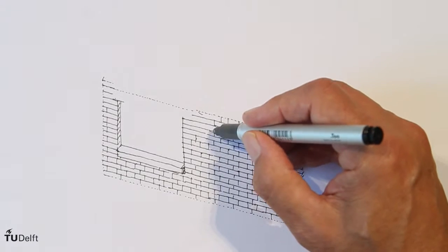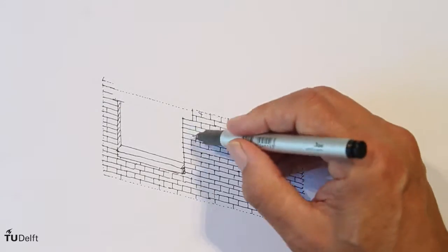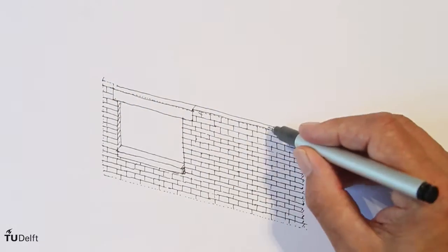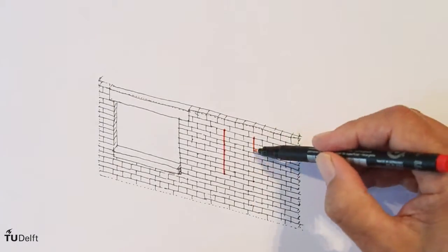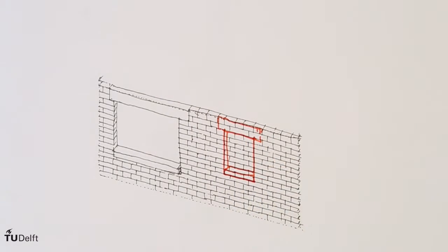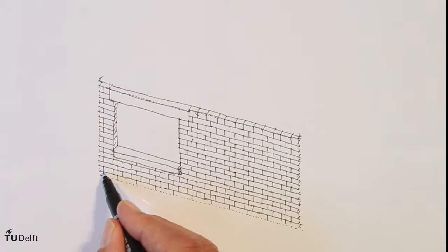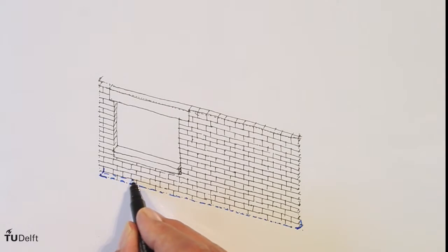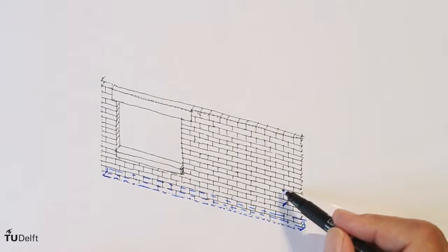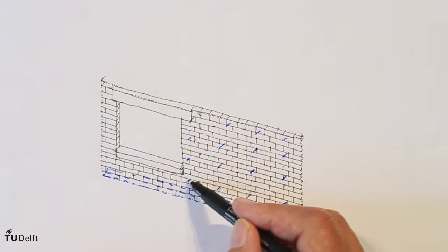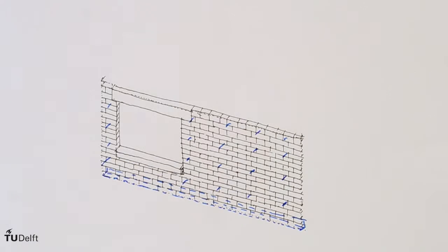The second consists of blocks such as fired brick, stone or concrete, laid in a pattern, a bond, and with lintels over an opening and window sills at the bottom. Openings are related to the dimensions of the blocks, in width as well as in height. The vertical load is transferred to a supporting element at the bottom, which itself is fixed to, by preference, the main load-bearing structure of the building. Horizontal forces are transferred by anchors through the thermal insulating layer, thus inevitably forming small cold bridges.